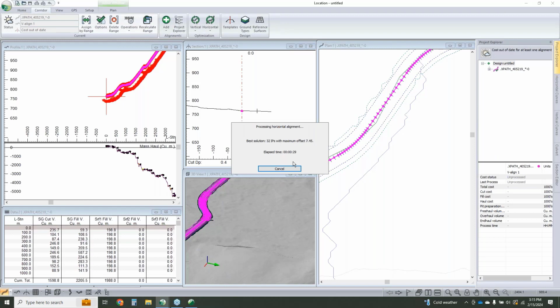And the other nice thing is this isn't just a tool that you have to use with the Path Explorer output as well. So if you have a surveyed center line that you'd like to use, that's not a proper alignment with curves, you can use this to fit it to that. If you have existing road line work as a shapefile or other vector format, you can use it for that as well. So it's a pretty useful tool.